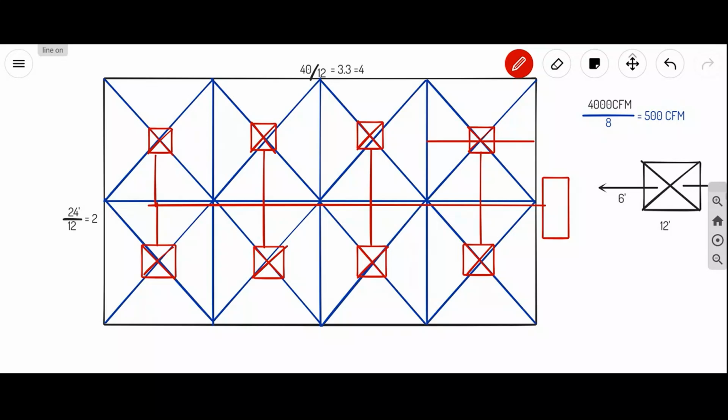Now, what happens in real time? Because we may not be seeing the real time. In real time there may be slight changes. Somewhere I'll take a short radius elbow, but there is a beam or column coming. So instead of a short radius elbow, the site engineer will take an instant decision and make a long radius elbow. So there may be little changes on the site.